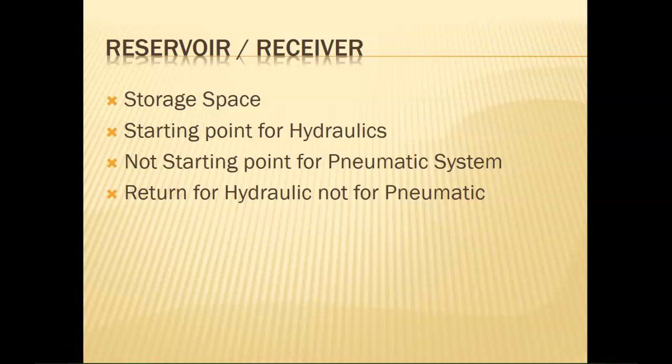With hydraulics, yes, that's where it starts because you have the pump that then moves it around the system, right? In pneumatics, it does not start there, it starts at the compressor. The good thing about pneumatics is we can vent it to air. It's why it's one of the most popular ones to use. Hydraulics have to be returned back to the reservoir, just like in your car, because otherwise you have a leak somewhere and you probably need to get that fixed, right?